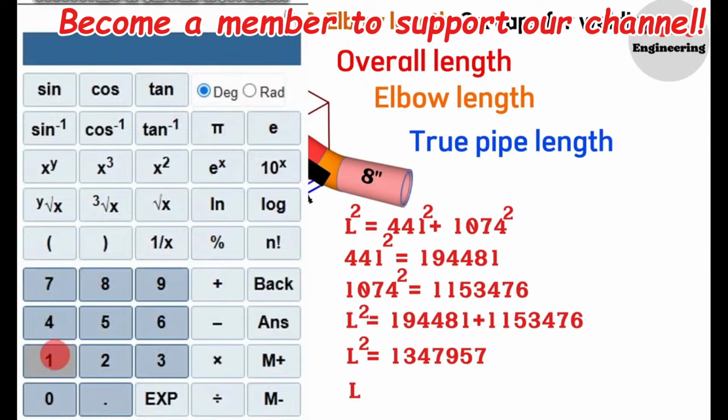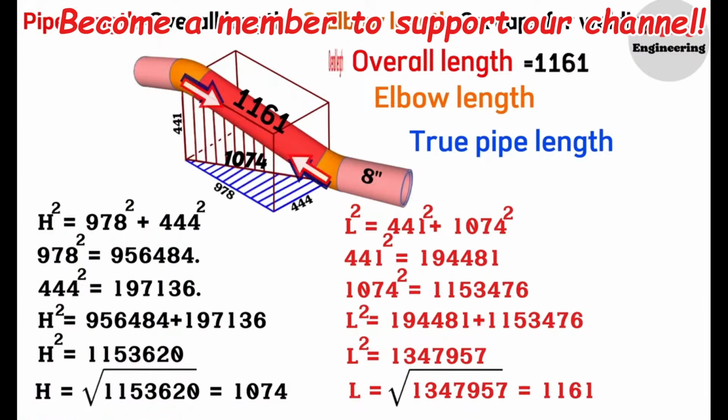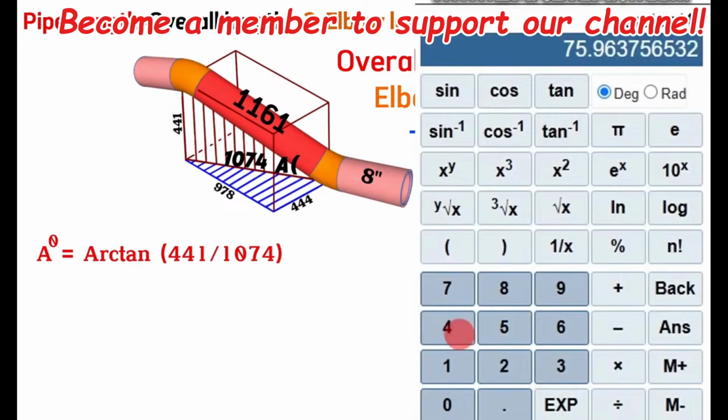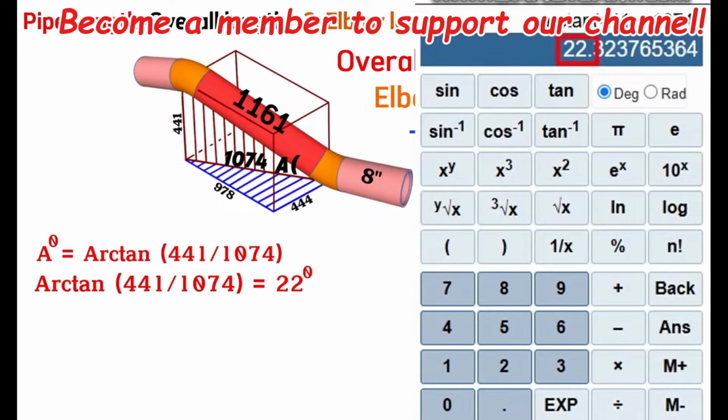Now calculate the elbow degree for these dimensions on this pipeline. To find the elbow degree, we will use the trigonometric function. So, if we denote this angle as A, then A degrees will be equal to the arctangent of 441 divided by 1074. Using a scientific calculator, the arctangent of 441 divided by 1074 will equal approximately 22 degrees. So, we calculated and found that the cutting angle of these elbows is 22 degrees on the 8-inch pipeline.